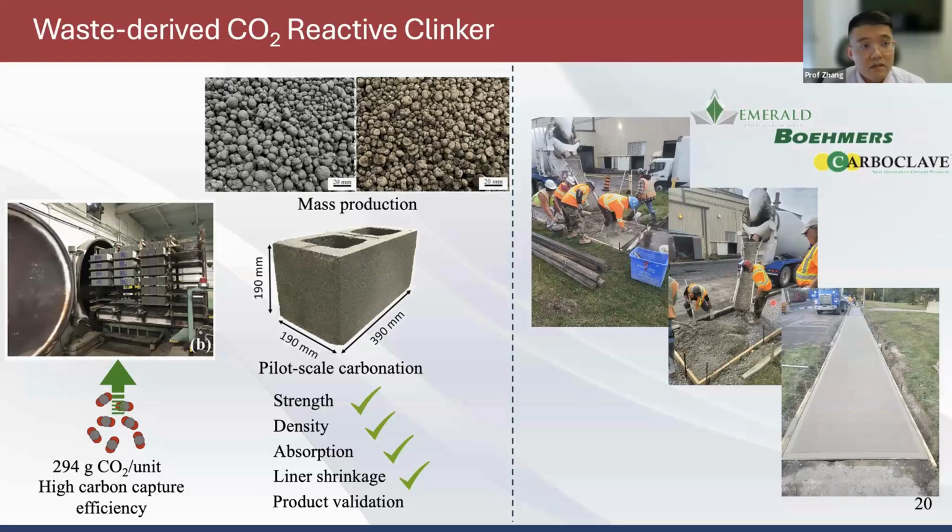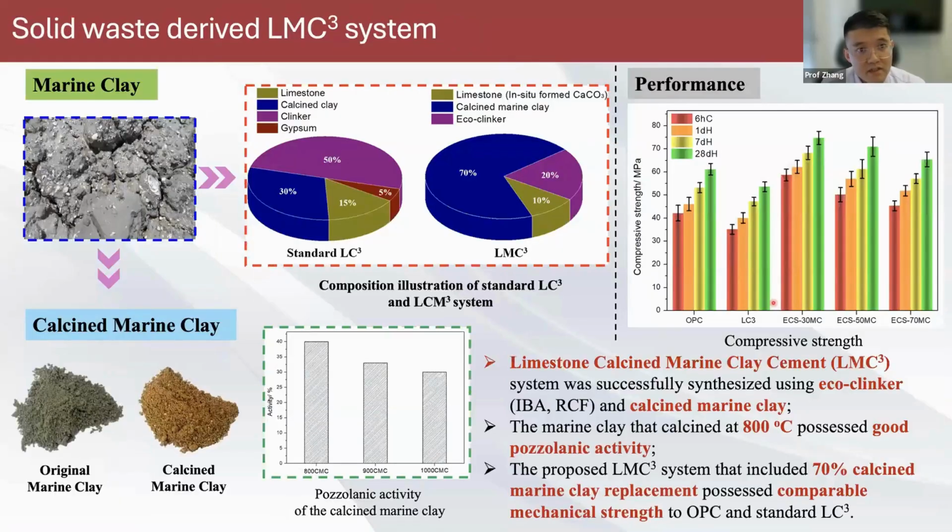Another cementing system we are developing is called the LMC3 system. In this system, we engage with a redundant resource in Hong Kong, which is marine clay. We can calcine this marine clay. We can activate the marine clay using pyrolysis at a not very high temperature, around 800 degrees C. We can see that it achieves a good reactivity.